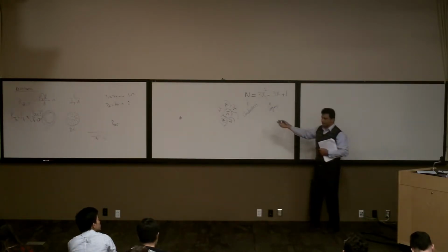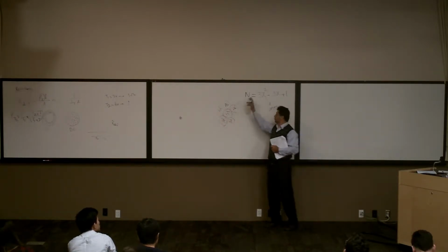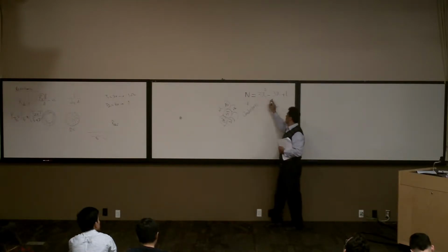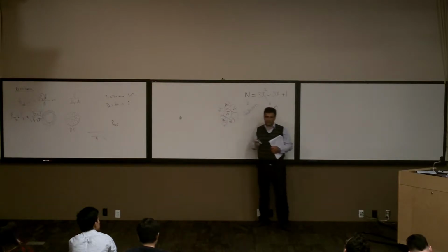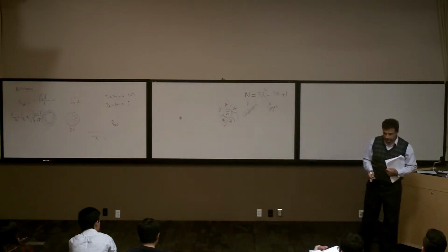So basically here, we have a two-layer system, right? Two-layer cable. If you put 2 here, it's going to be 3 times 4 is 12, minus 6, plus 1 is 7. You have 7 conductors. This is the way we build these cables for transmission lines.